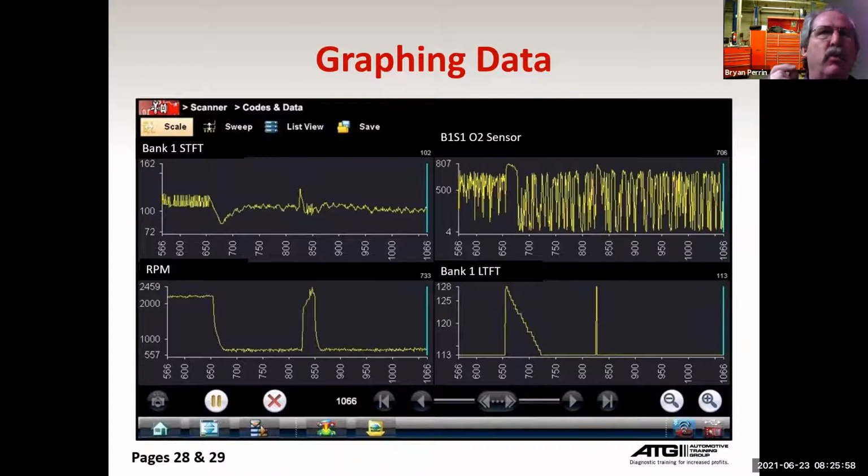So my question was, since I only have one O2 sensor, and the one O2 sensor is on one side, and how this engine works, it's a V6, and it has a pipe that comes from this side over to the other side of the engine, has all 3 on this side, and then the O2 sensor is right here. And so it's like, okay, is it possible I have a balance issue where not all the injectors are working correctly? Okay, possible. How do I prove that? I mean, how can I prove it?